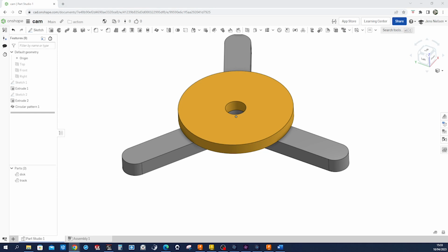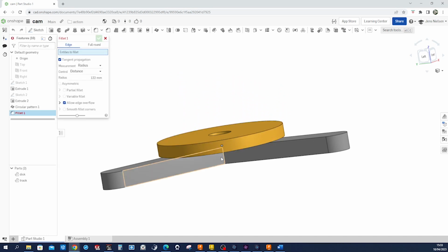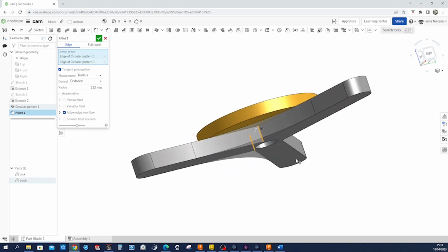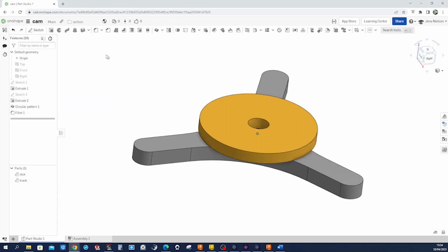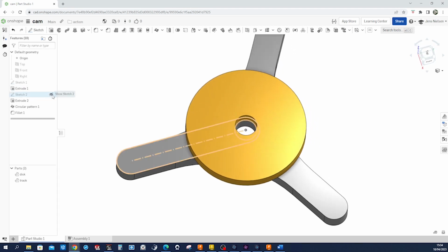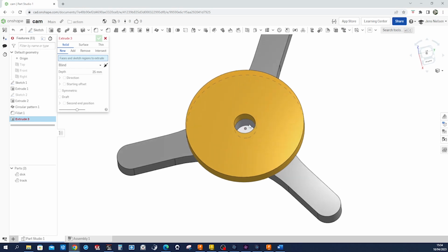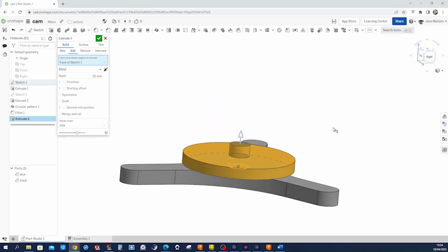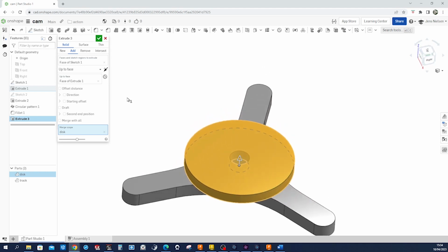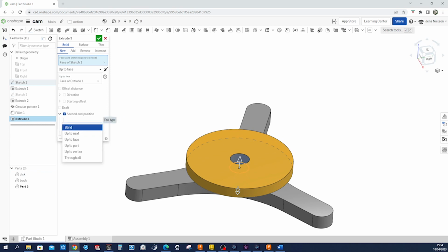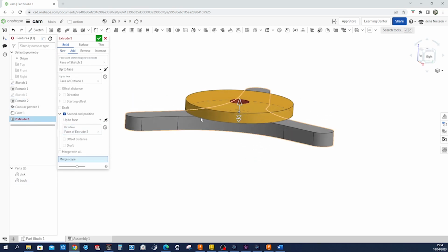Okay. Give that a big fillet. 122. That edge, and that one. Then extrude. We still got here, that's our first sketch. I want to extrude that region up to that face, and a second end position up to that face, adding to our disk.